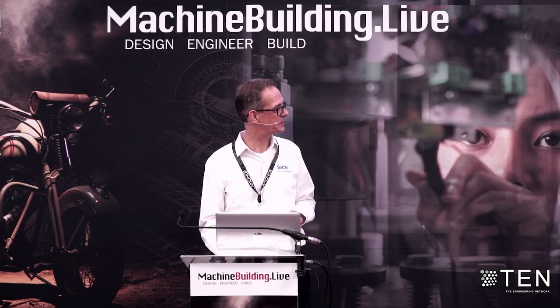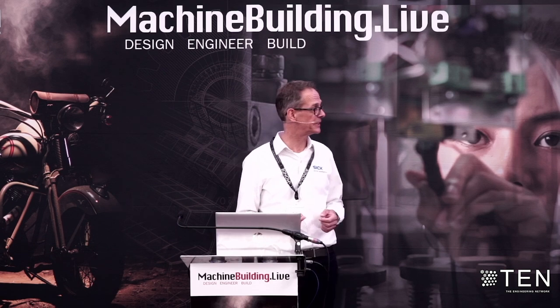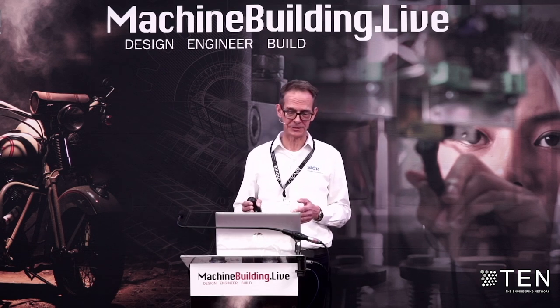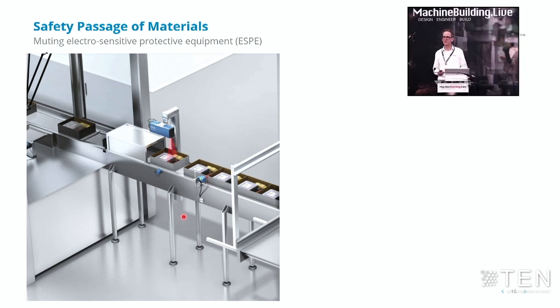And my final example of an innovation in entry-exit is looking more at small items going through a packaging machine or box erector. Typically, we would guard these access points to prevent reach-in of an operator using a physical tunnel. And a physical tunnel depends on the size of the opening, how far the tunnel extends beyond the machine limit. Typically, a minimum of 800 millimeters length to stop someone putting their arm into a machine would be the requirement.